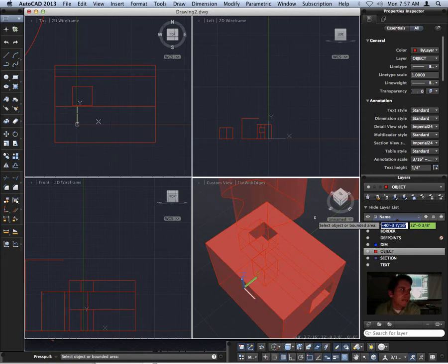So press pull, kind of a fun, quick, and easy way of modifying objects and converting two-dimensional objects into three-dimensional objects. So today your assignment is to create that Swiss cheese and just note the dimensions on it when you draw it, but obviously all your circles and everything are random. Any questions on press pull command?